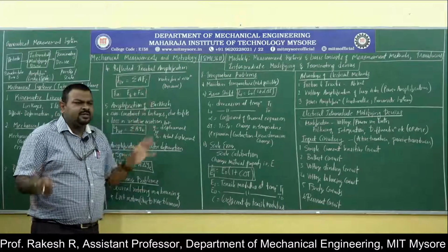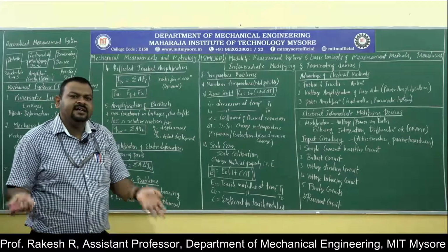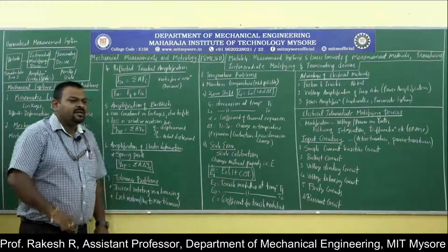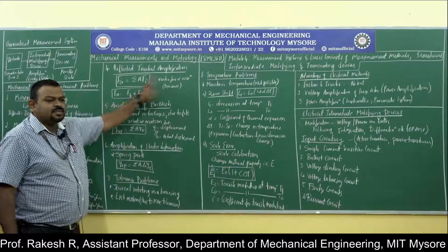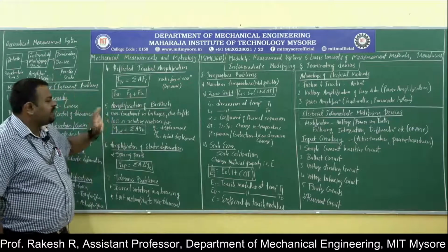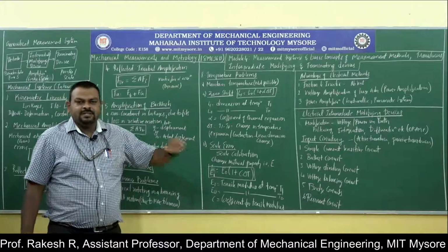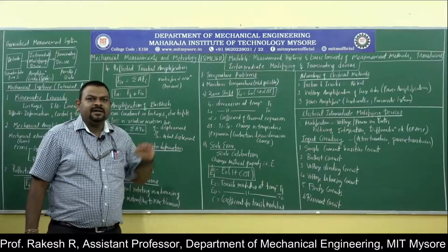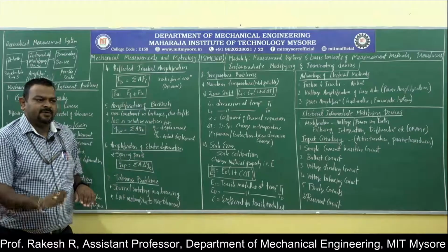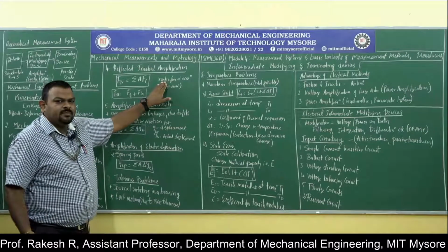And there is no reason for inertia force to be set up. Dynamic forces can be set up at any time, anywhere. We cannot predict that very easily. There will always be dynamic forces, always inertia forces, and it cannot be fixed completely. So inertia forces will be there in the vehicle, but they can be reduced by proper balancing of reciprocating or rotating masses. Inertia force will be developed.